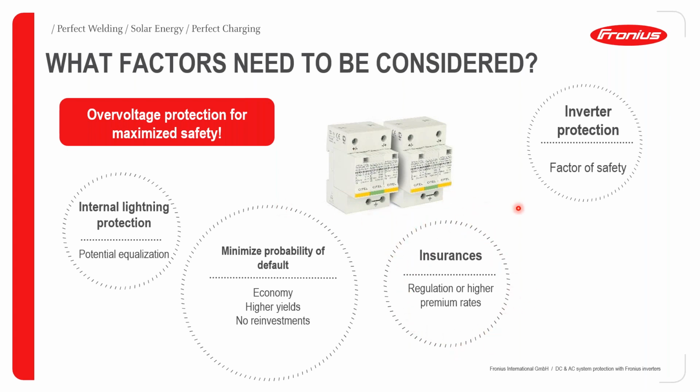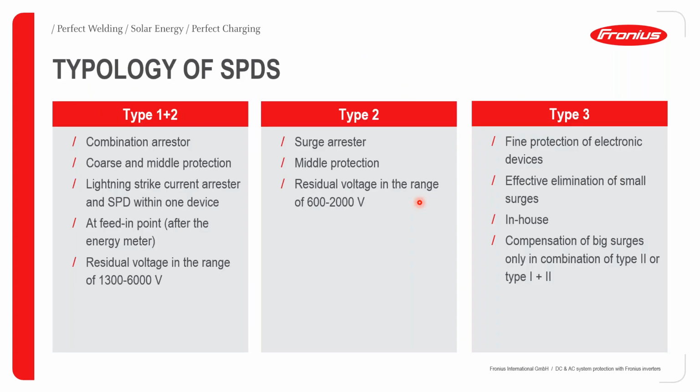And then in terms of inverter protection, that becomes a factor of safety as far as the inverter operation is concerned. Then for Fronius inverters, as we have seen, if you do require at any one point, if you had not ordered the inverter with OVPs, then you can very simply retrofit OVPs into any Fronius inverter.